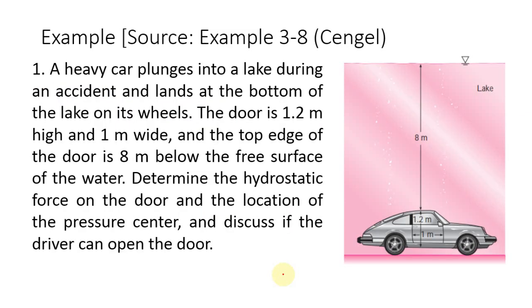So let's look at an example, and here we have a heavy car which plunged into a lake during an accident, and it lands at the bottom of the lake on its wheels, and the door is 1.2 meter high and 1 meter wide, and the top edge of the door is 8 meter below the free surface of the water, and we're asked to determine the hydrostatic force on the door and the location of the center of pressure, and we are asked if the driver can open the door.